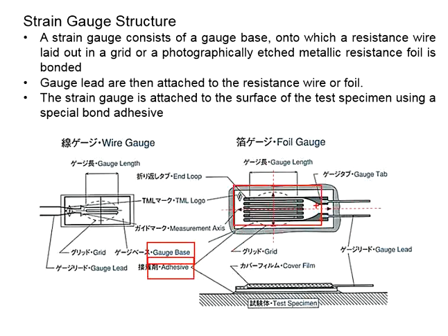By measuring the change of resistance, we are able to determine the strain happening within the sensitive element, and it is assumed that the strain as measured by this sensitive element is equivalent to that of the test specimen. This is provided that the gauge hysteresis is overcome.